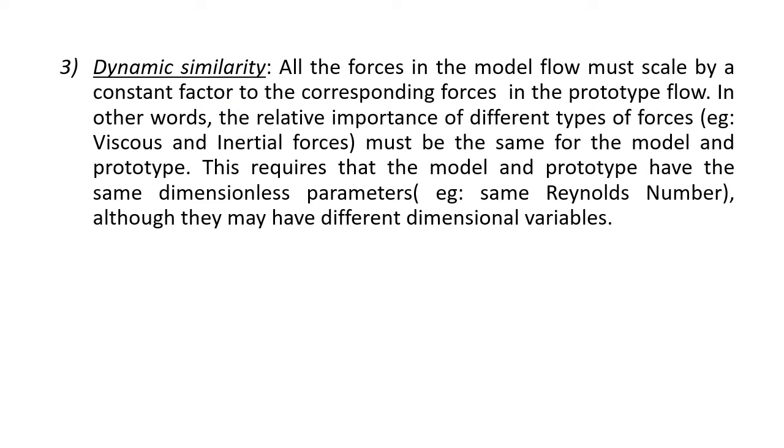And the last similarity is dynamic similarity. All the forces in the model flow must scale by a constant factor to the corresponding forces in the prototype flow. In other words, the relative importance of different types of forces, for example viscous and inertial forces, must be the same for model and the prototype. This requires that model and prototype have the same dimensionless parameters like Reynolds number, although they may have different dimensional variables.